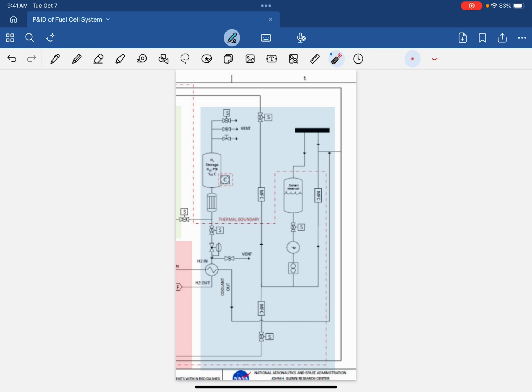They actually have many uses. If the pressure is too high, this pressure relief valve is going to allow excess hydrogen to flow out. If the workers want to manually release some pressure, or you want to use the hydrogen for something else, they can release it with this gate valve. And so there are many uses for these valves.